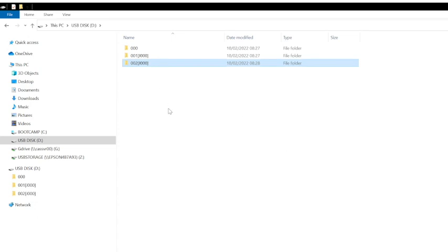Just to show you, if you want to use contact inputs 3 and 4, the folder names are slightly different, because the player itself can actually handle up to 15 combinations of those 4 contact inputs, which will allow you to play up to 15 different folders. We sell an additional add-on board from Wave Systems, which allows you to easily connect up 15 trigger inputs to the 4 contact inputs on the back of the player.